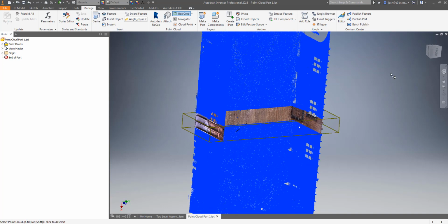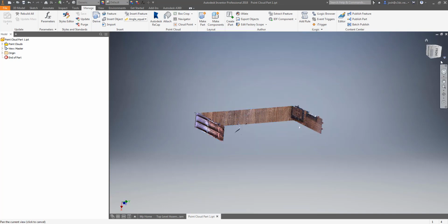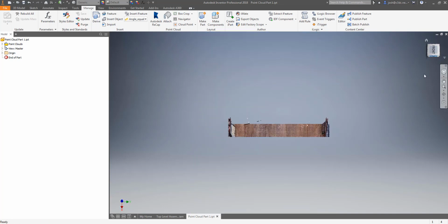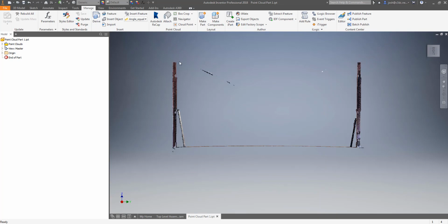To most people, 10 to 15 millimeters might not sound like that much, but let's put that into the perspective of a plant model where we might be adding steelwork or a pipe or something between these walls. If they are both 15 millimeters out of square towards each other, that's a total difference of 30 millimeters or 3 centimeters, or for our imperial using brethren, a little under 1.25 inches. If this issue wasn't picked up until the day of the installation, then it could potentially cost tens of thousands of dollars in reworks and delayed deadlines.